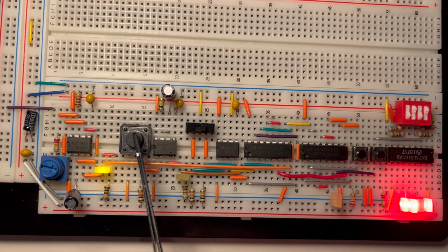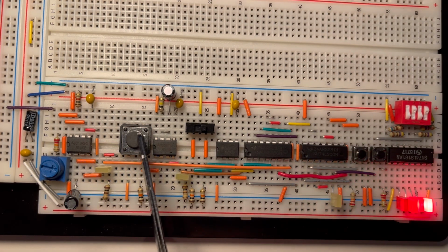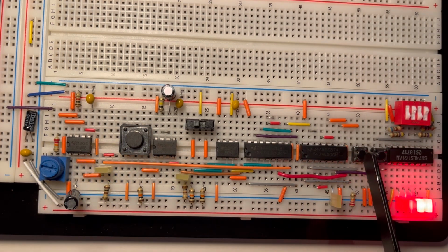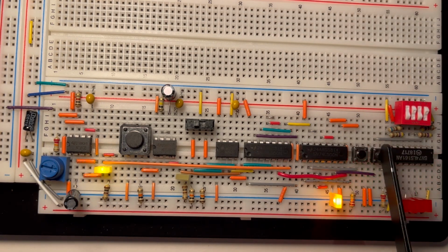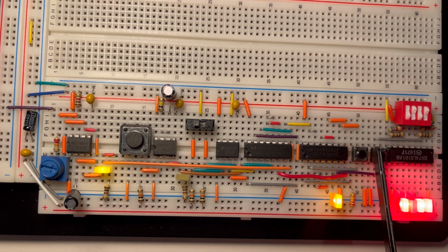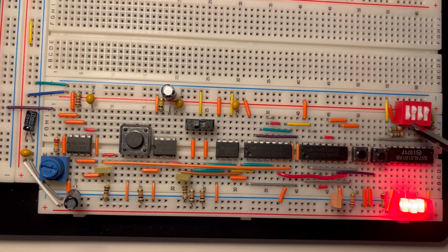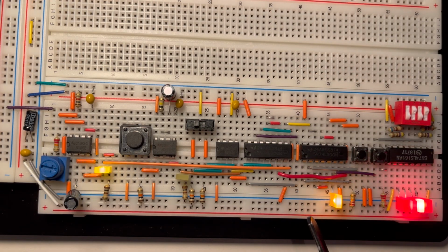In manual mode, one press of this button will cycle 1 clock cycle. This button can halt the counter by preventing the clock signal from being passed through, and this button will cause the program counter to go to the binary value inputted on this DIP rocker switch. This feature allows us to simulate a branching instruction, which will eventually become important as it allows us to go to specific lines in our program, and it'll be influenced by the address buffer and control ROM.